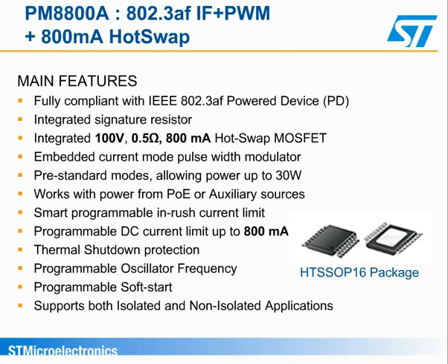The PM8800A integrates a fully compliant IEEE 802.3af interface together with the 25 kilohm signature resistance and a current mode PWM controller.